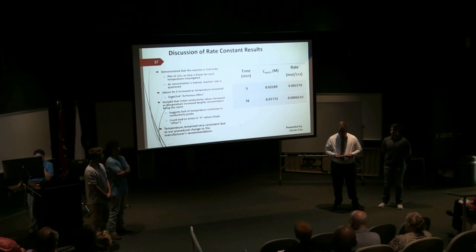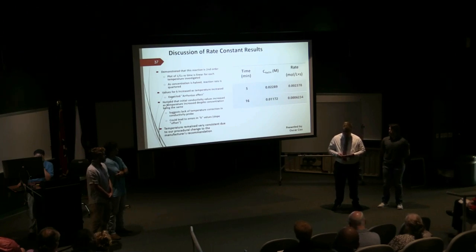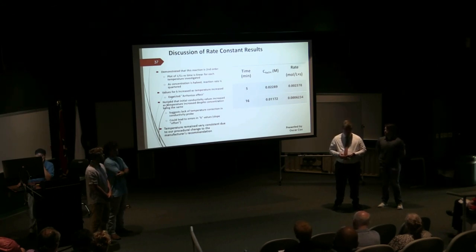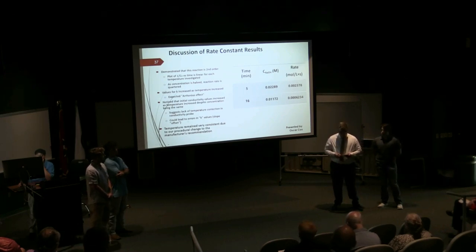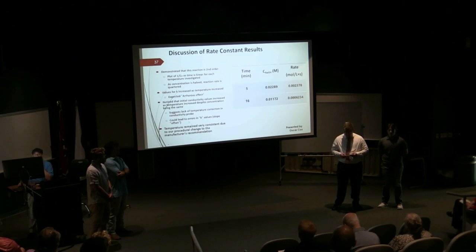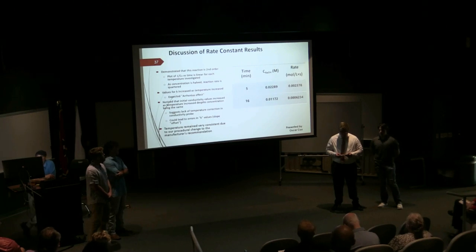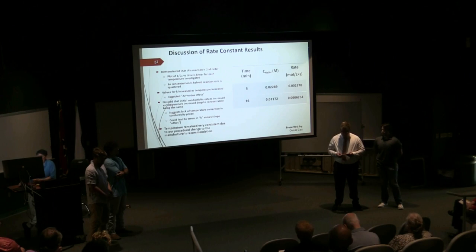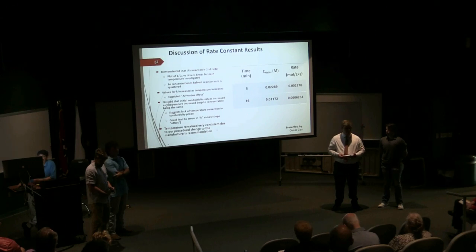Despite having the same initial concentration of sodium hydroxide for each experiment, we noticed that the initial conductivity increased as temperature increased. This suggests that there is a lack of temperature correction built into the conductivity probes. We suspect that even though our plotted information was linear, there could be an offset in the slope value and some error in the rate constant. Our temperature remained very consistent throughout the run, so we think the procedure change from the manufacturer was very beneficial.